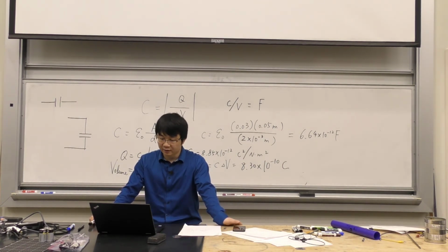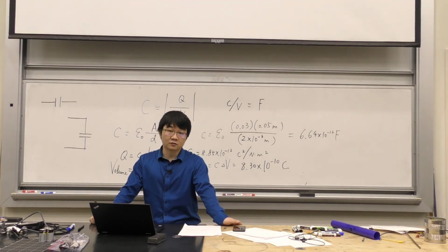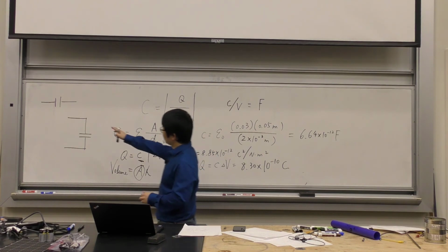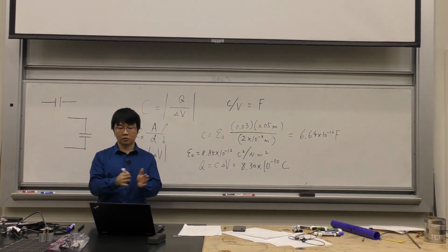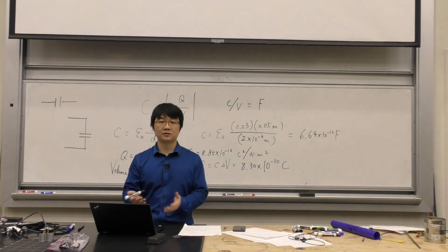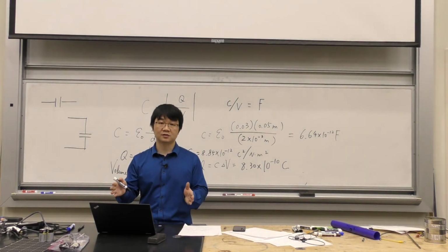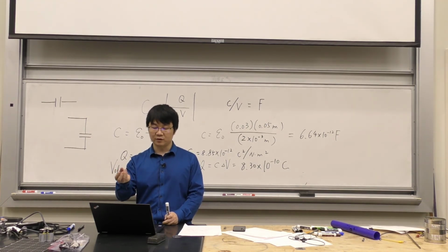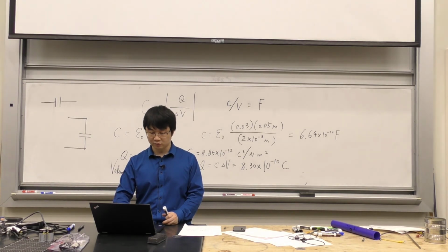And also, it's going to make sure these two metal sheets are not in actual contact, right? Because if they are in actual contact, then if one plate carries positive charge and the other carries negative, all these charges are going to be neutralized. So it's going to get discharged. You don't have them separate, you don't have them saved, right? So that's why dielectrics are widely used in capacitors to make the capacitance bigger, increase the breakdown voltage, and also maintain these parallel plates without actual contact, to make sure they don't get discharged.